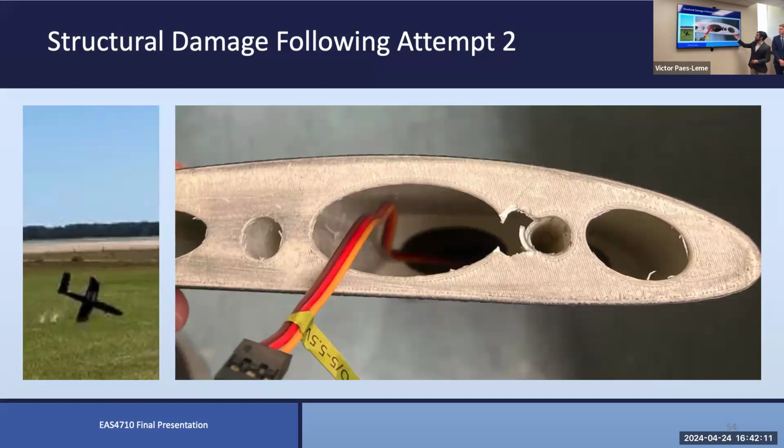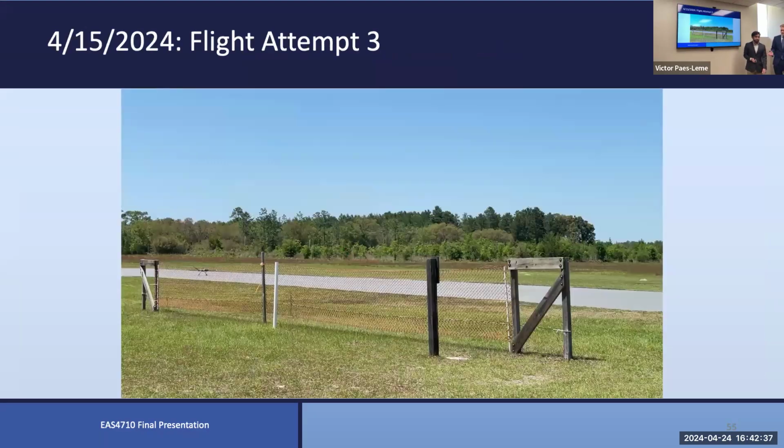And you can see on this image here that because of the high amount of area that we provided for the carbon fiber spar that we're using to hold the wing in place, it was enough to take the bearing stress of the impact itself. And both of these pictures represent the wings that we were able to use in subsequent test flights. They were still very much airworthy afterwards.